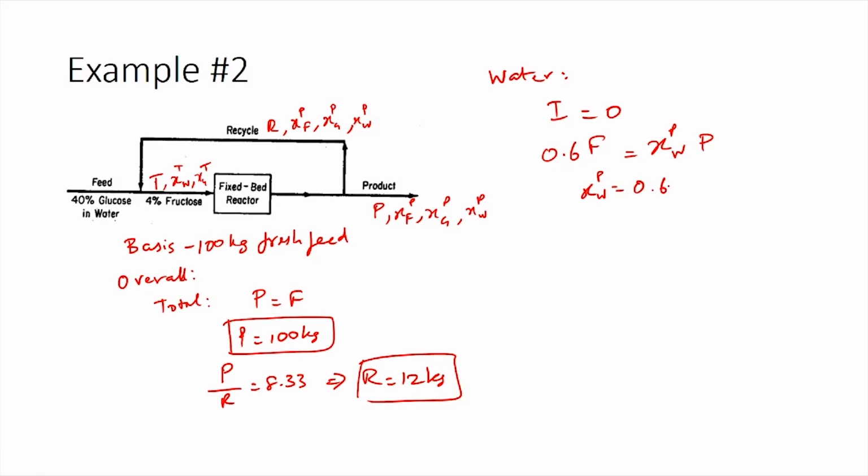So, now the next step is for us to get information about the mass fractions of the product streams, recycle streams and the gross feed. For finding this information we need to choose an appropriate system. If we were to choose the splitter, we would be able to write only one independent balance equation. Hence, it would not help us in identifying all the unknowns. So, we can choose the mixing point instead, where we would be able to get more independent equations and hopefully we will be able to solve for the unknowns. So, let us take the mixing point as the system.